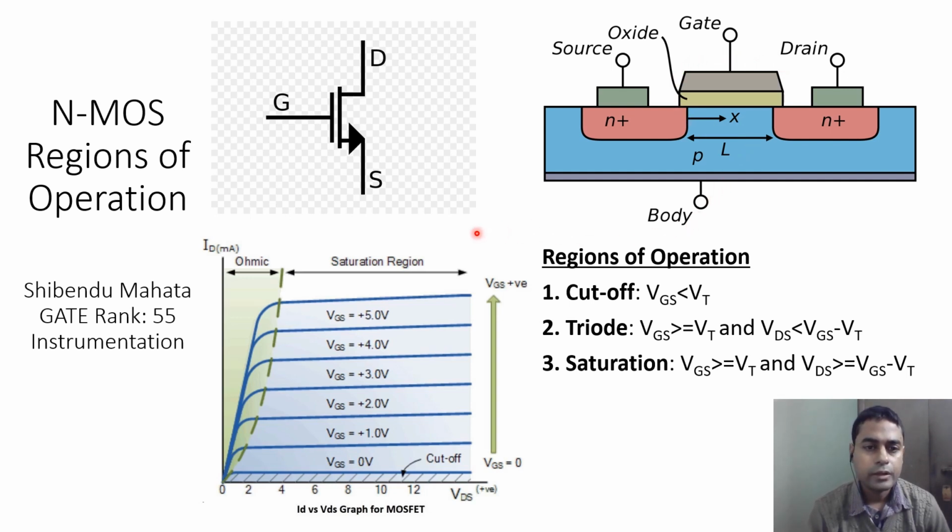Next, we look at the drain to source voltage versus the drain current, or drain to source current, of the N-channel MOSFET for various values of gate to source voltage. So this is gate to source voltage of 0 volt, 1 volt, 2 volt, 3 volt, and so on. Now note that this is obeying 3 different segments of behavior.